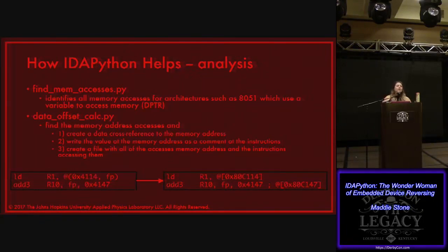Another key point is that in a lot of these different architectures, you're working across segments or external memory. So how are these addressable? I haven't added it in yet because I'm still trying to come up with the best way to make this processor agnostic. But let's say in C166, they only use 14 bits of the address. The top 2 bits say which page you're going to be in, and then you do the calculations and add it. I've been able to do that for specific databases, but I'm trying to think about how to make it processor agnostic, to help you when you're working with things like PIC and C166 that have these page pointers throughout.